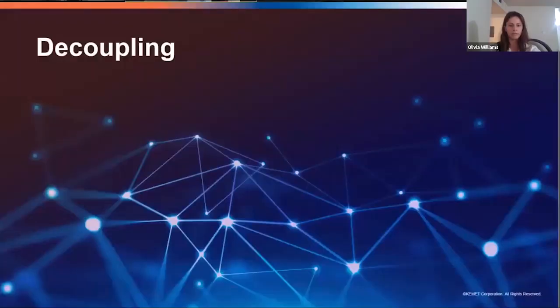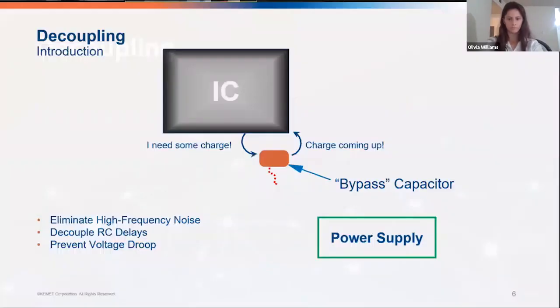First, we'll go through the decoupling and take a closer look. One of the most prevalent uses of capacitors in low voltage DC designs is to decouple the IC from the power supply circuitry. Basically the IC can use this set of capacitors and bypass the power supply if or when needed, which is where they get their other name, bypass capacitor.